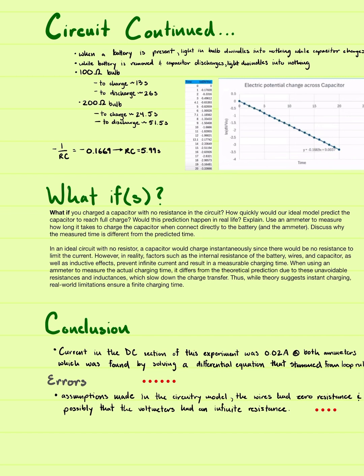In the next part, an RC circuit with the components shown on this page was constructed. The circuit was then closed to allow the capacitor to charge. Then the battery was removed and the circuit was closed again to allow the capacitor to discharge. At 1 second intervals, up to 20 seconds, the potential difference of the capacitor was measured. Finally, the plot of the natural log of the potential difference divided by the initial potential difference was taken over time, and the plot gave a linear slope, which is then used to calculate the time constant of the RC circuit. The RC circuit's time constant equals 4.94 seconds.